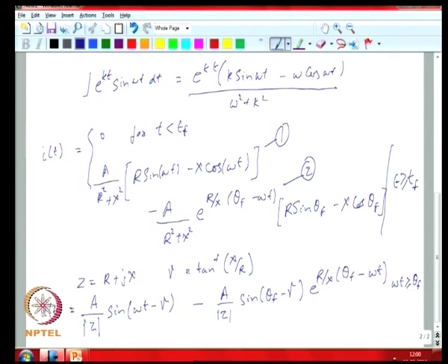So, when you do 3-phase fault analysis or sequence model analysis, what you are actually getting is the first term. The second term is essentially a transient component, and typically when you look at dynamical systems, you assume that the transient component is being caused by initial conditions.